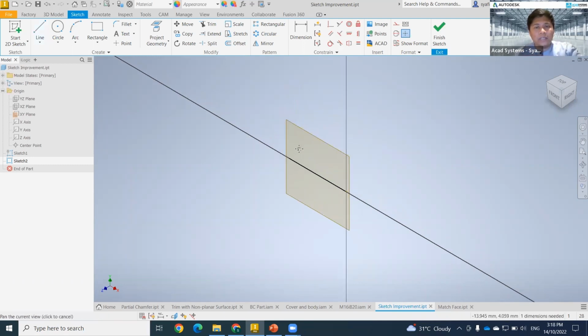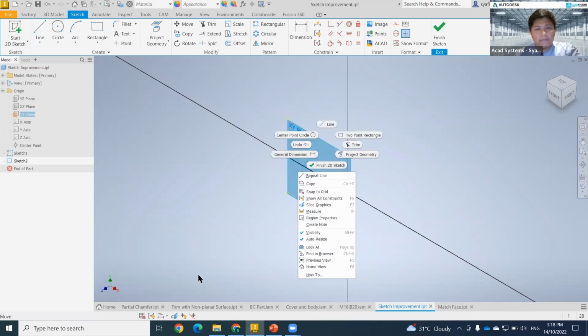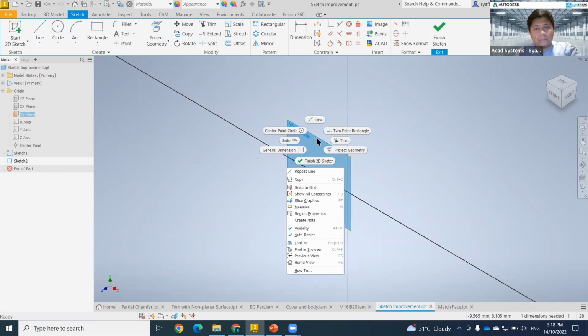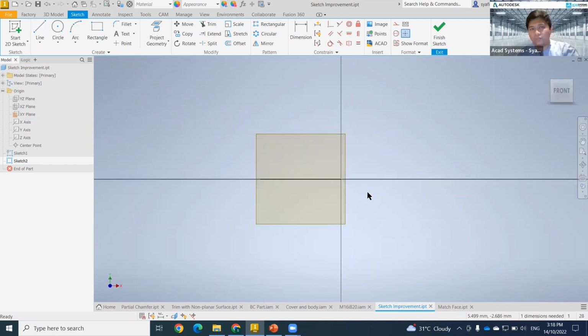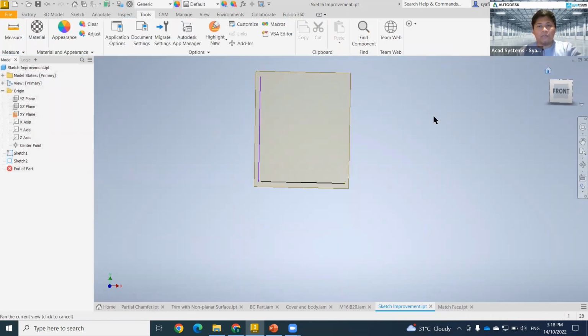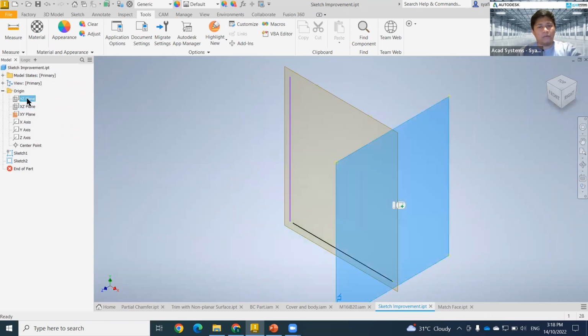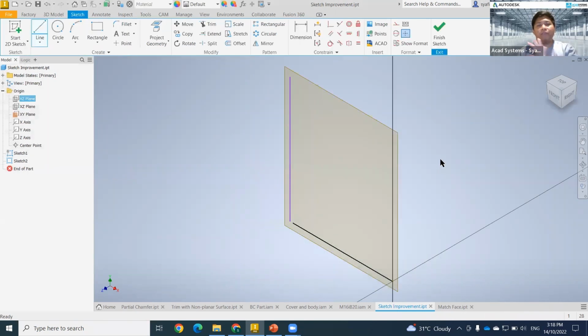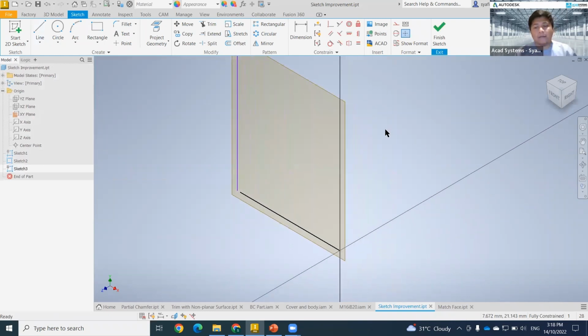Later, after you are done with these things and you want to go back to this view, you can simply right click and then click on this Look At. It will also rotate for you. Some people prefer that every time they create a sketch, it has nothing to do with rotation. They don't want the view to keep rotating. For example, here I want to create a drawing from here. So new sketch, it will stay fixed like this. That will be the example.